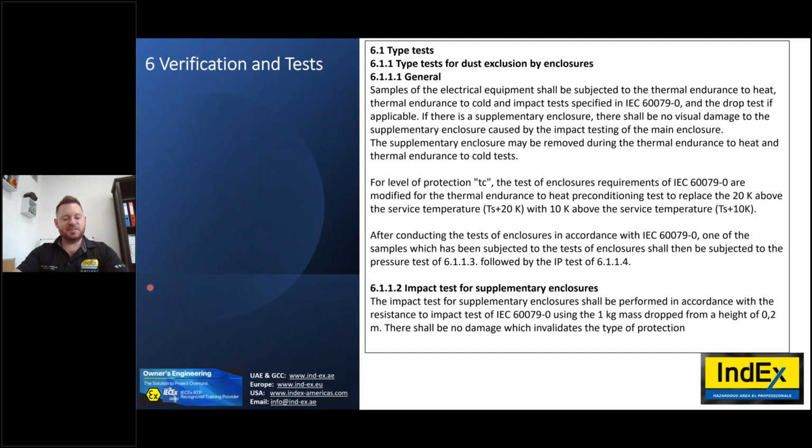Would I install a seal? If I'm close to a zone 20 or the equipment is in a zone 20, yes, definitely I would use a conduit seal. If it's a zone 22 everywhere, typically not. It's more of a risk assessment method. You need to consider where you transition between different types of zones and have a bit of common sense.